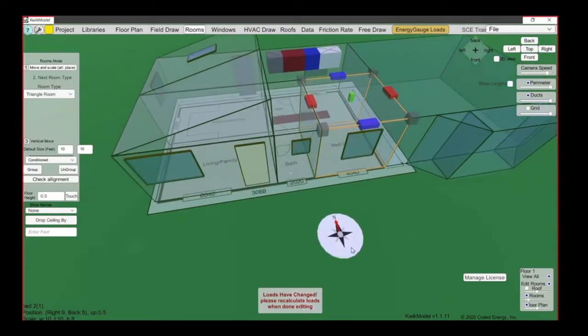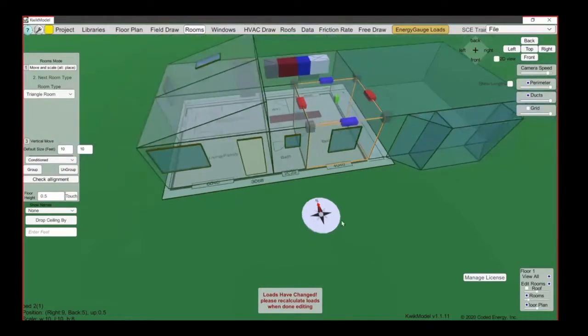Now, the other thing I didn't talk too much about yesterday was this harmless looking little circle. Connor, make it so I can see what they're seeing, please. This harmless little white circle down here, okay, called a north arrow. And if you're doing cooling load calcs, that's a very, very important little thing, because the direction of a window has a huge impact on how much heat is coming in through that window in the form of solar gains.